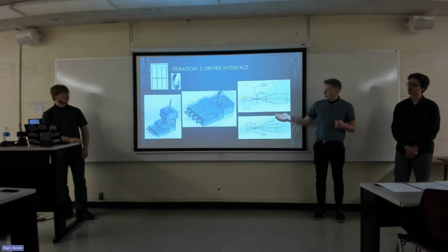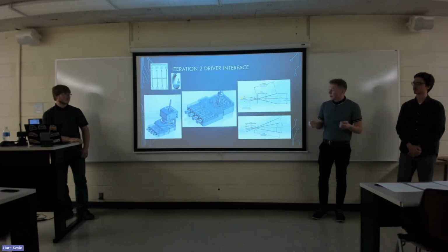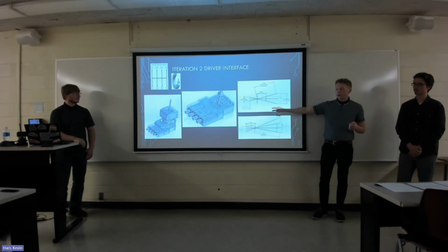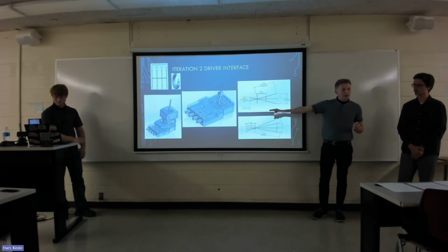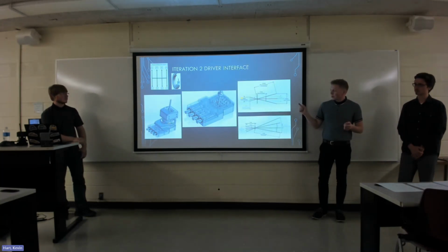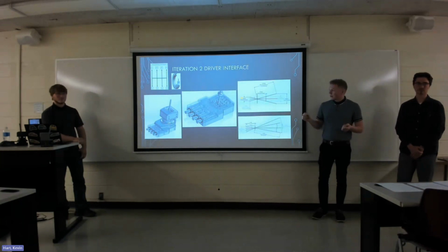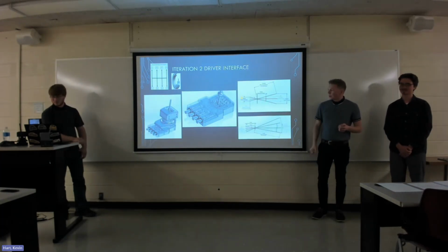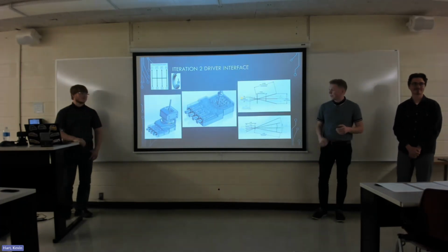Where the major change came from was trying to make this a fluid-filled system to reduce friction within the assembly. To do this, we needed to transition this rectangular output rod into a cylindrical output rod so that we could fix cylindrical shaft seals on the end of this assembly to retain all the fluid we fill it with. In doing so, with one of the smallest seals that would safely transmit the force, it increased the base and the width of this lower assembly, but we were able to accomplish that goal of having that fluid fill with iteration 2.